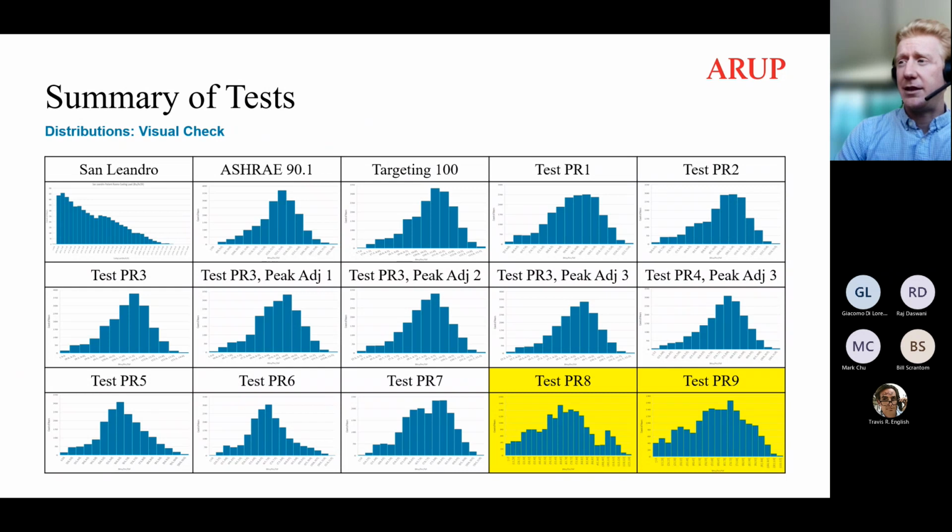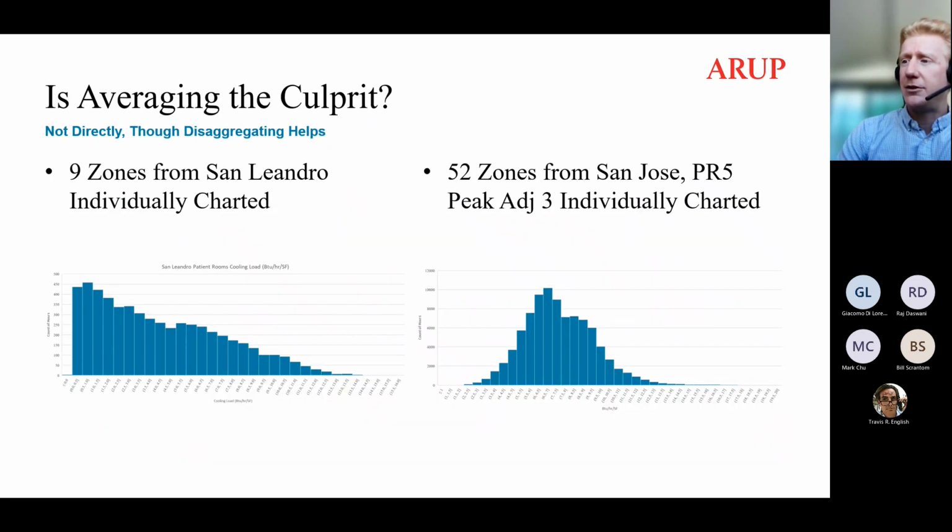One thing to note here is looking at the outputs from the energy model, there's sort of 2 ways to compare this. The data that was present in those prior reports was taking all of the points out of Clockworks data for all of the patient rooms and stacking them up together, whereas the initial grouping here from the EnergyPlus model that was run is looking at the zone group for patient rooms. So that does create some effective averaging.